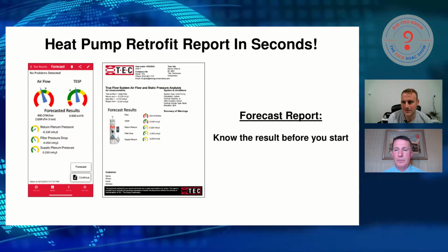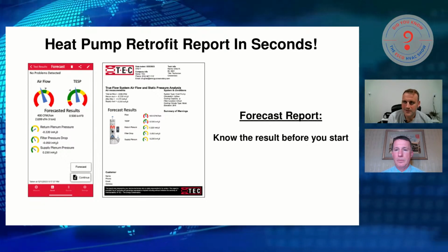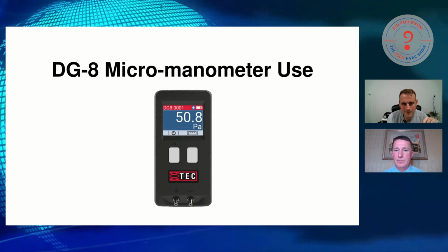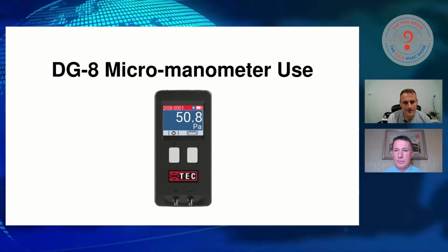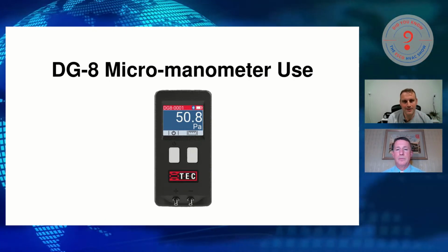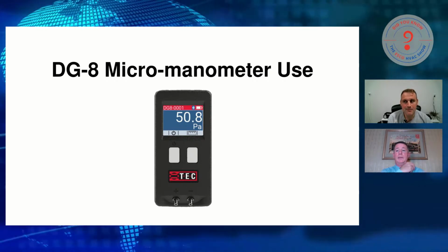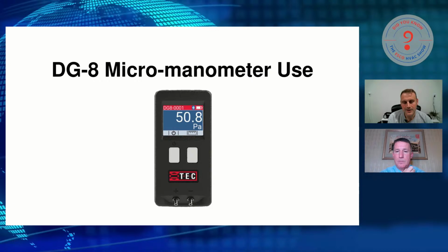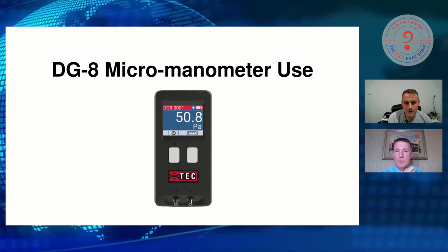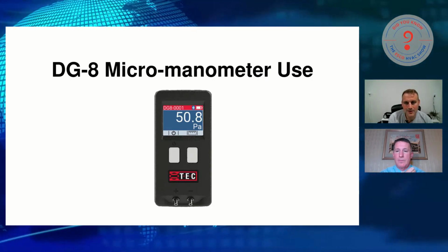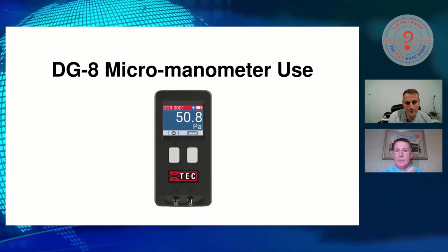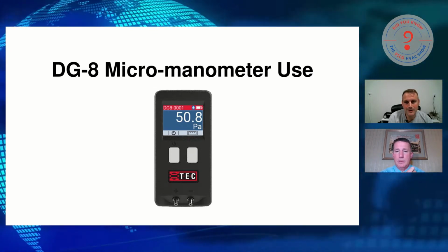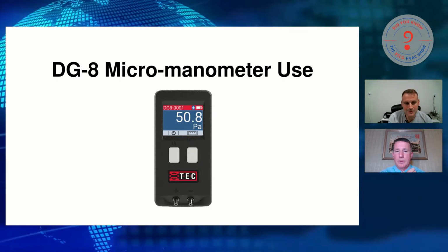But here's my stepping stone. If you're going to take static pressure measurements, my advice is get a micromanometer, not a manometer, a micromanometer, right? Get something that measures in pascals and measures accurately in pascals. So this is our DG8 micromanometer. We created this gauge mainly to work with the Trueflow Grid because if we had to throw our DG1000 at it, it was going to raise the cost about another $1,500. So we had to come out with a single channel manometer that was less expensive.